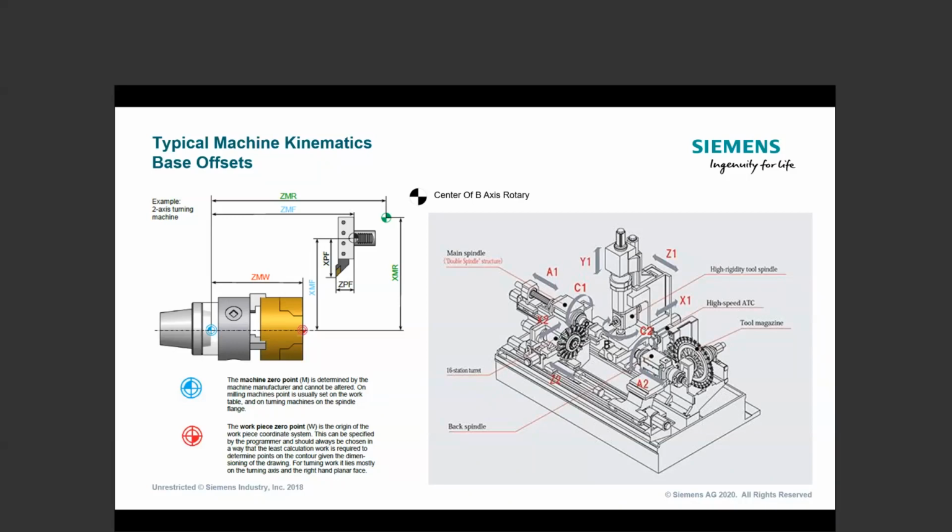And then generally from there, when you get to this type of technology, you want to work from a gauge line. So we're going to get into that a little more, but I expect to see all of my tool offsets be a positive distance from the spindle face or wherever gauge line is on that taper technology to the tip of that tool. But everything's going to back up right off that main spindle. So that's where our primary datum should be. And if you're running into handoff problems, and your machine was not commissioned there, that's probably why you're running into handoff problems. So it's a good thing to always commission them building off of that main spindle.